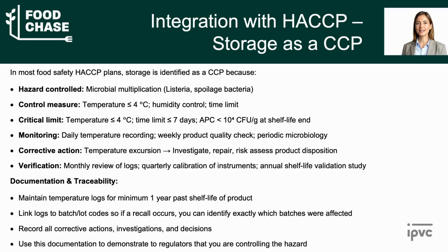Storage management is not just best practice, it is a regulatory requirement. In your HACCP plan, storage is almost always identified as a critical control point because it is where you control microbial multiplication. The hazard is Listeria or other pathogens growing and reaching unsafe levels by shelf life end. The control is temperature, keeping it at 4 degrees or below.